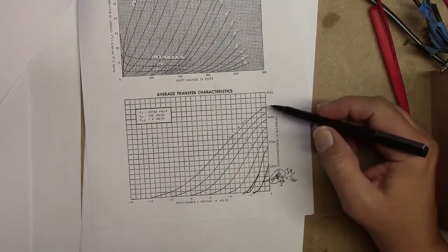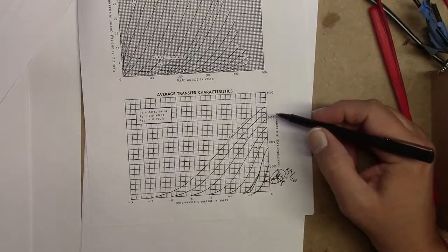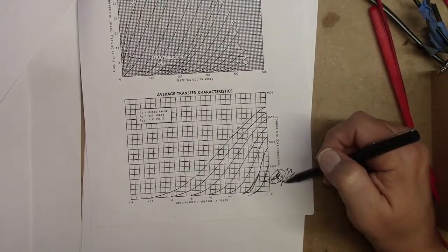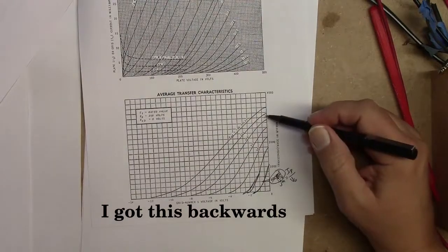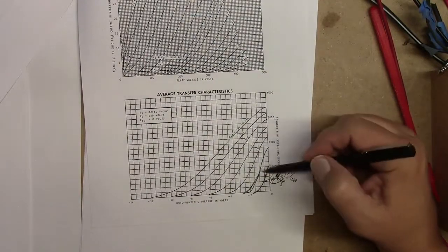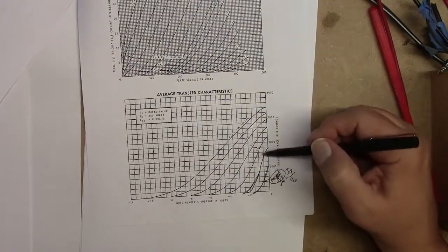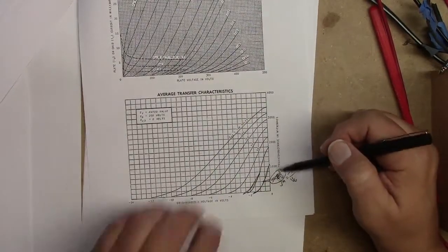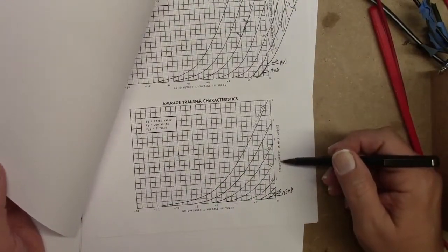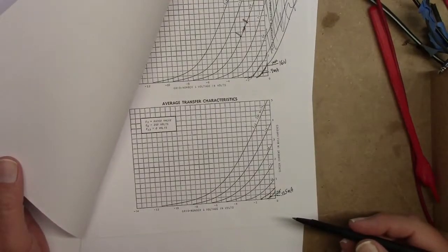Because if I say I wanted a 5 volt swing on the plate, down here this is such a low voltage, I could use a very low resistance. If I use it up here, I need a larger resistance. Is that right? Yeah, I think that's right. Anyway, because of the screen voltage, it lets me have a lot of flexibility in all these different parameters in terms of G sub m, the plate current, the grid current, the screen current. All this stuff is pretty much variable. That's the key to the whole thing.